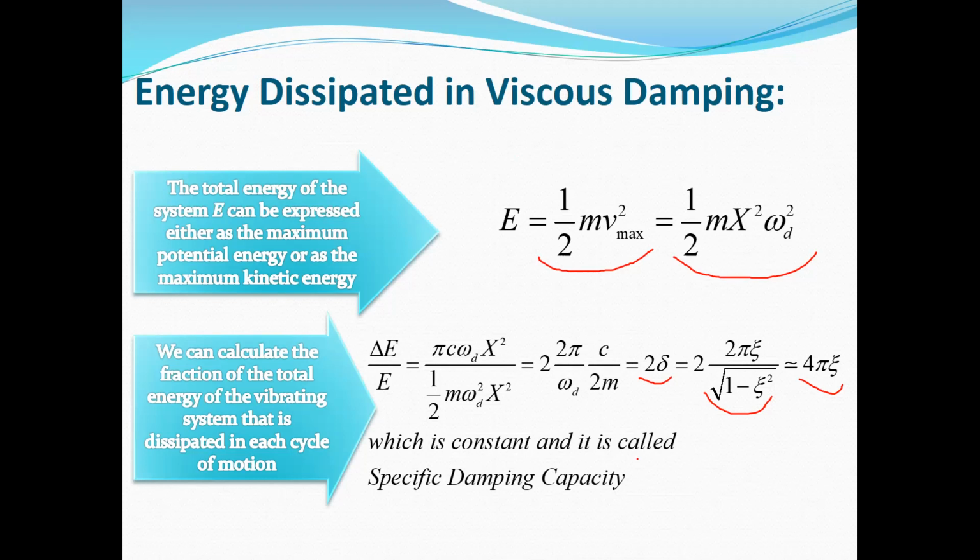And we prefer to have a linear equation of motion to solve. So for this purpose, we need to obtain an equivalent damping constant and an equivalent damping ratio for the system. By using this formula, we can obtain an equivalent viscous damped system, for example for a Coulomb damped system, to obtain a linear equation of motion.